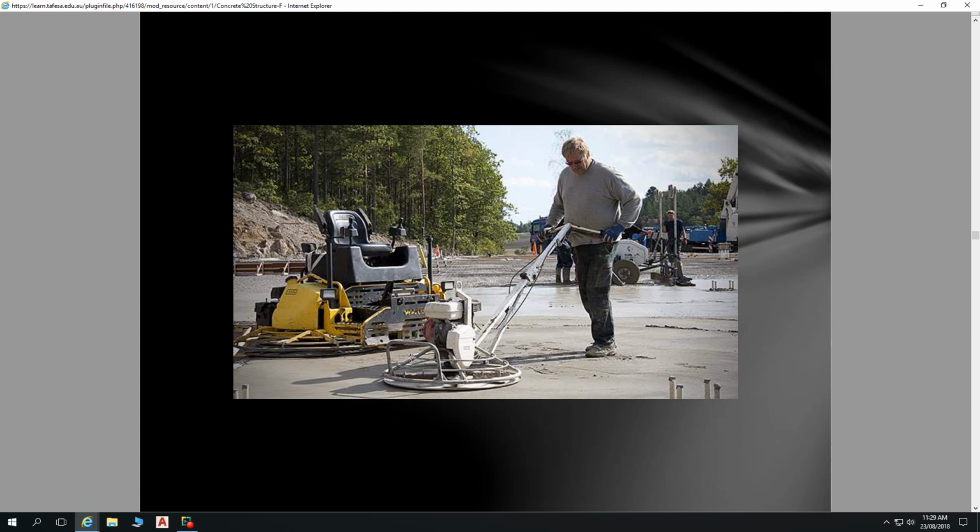With this sort of setup, would this show up as cracking? It may show up as cracking because that's the point of weakness, and you've got various different forces acting in various different locations. If you've got a patch which hasn't been vibrated properly, it looks fine from the top, but it's all loose down the bottom. That might be the place where it cracks, even though your forces are happening elsewhere. Yeah, because from the top it looks okay. Until something goes wrong. Exactly.